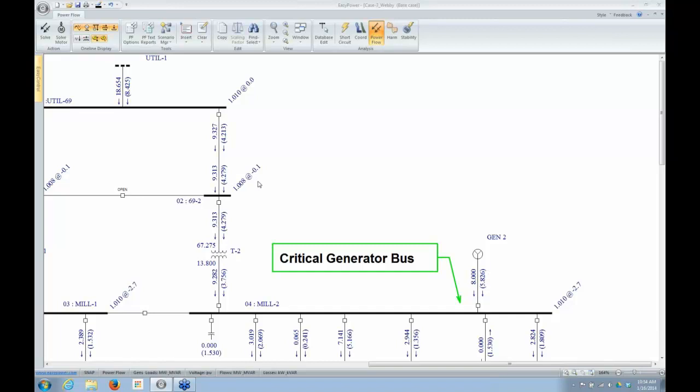Generator, if PV and you hit a megavar limit, does it crash or convert? It doesn't crash. You'll just get an error message that says it couldn't converge. So what I typically do is, in those generators, I would increase the VAR limits to whatever the max is, 10,000 megavars, I think, plus or minus, and see if I can get it to converge, then at least I can start to narrow in on the situation.